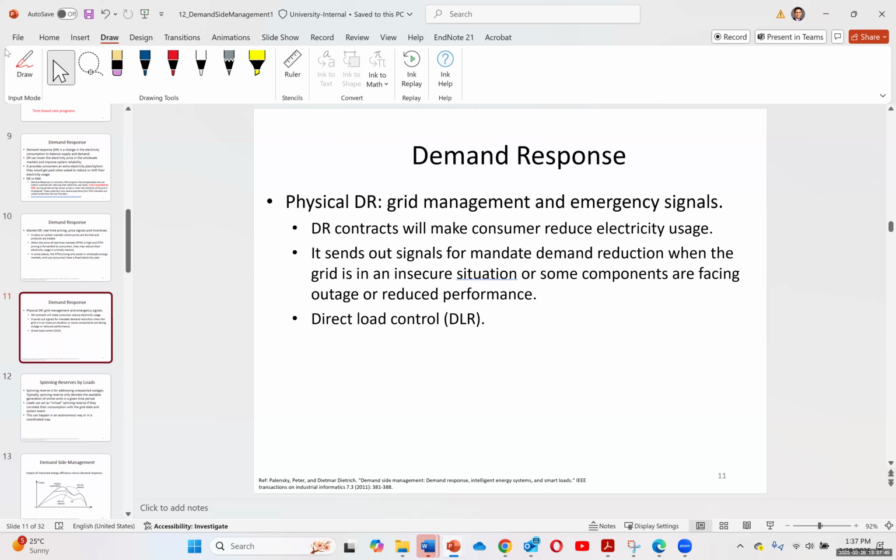So usually when you have a digital power meter, you have the time of day use, or time of use, or TOU system. The older analog power systems, because it costs a lot to upgrade them to be able to calculate the power during different times, use a bulk flat rate price, which is an average between a lower price for off-peak demand and a higher price for the peak demand.